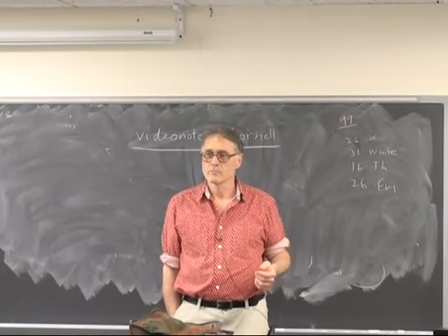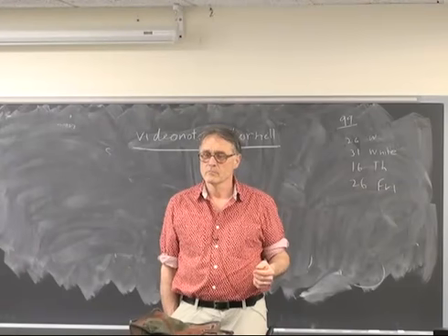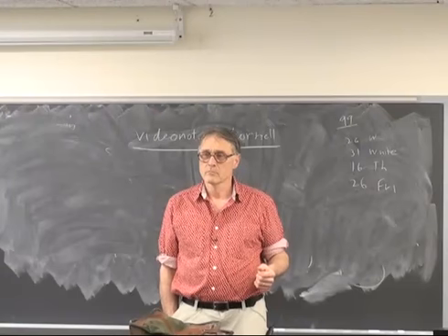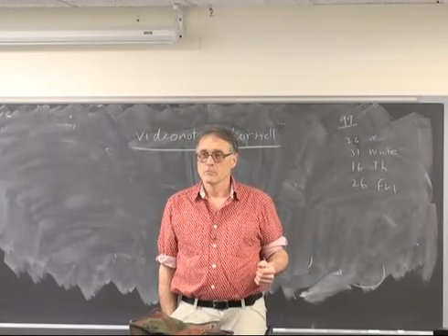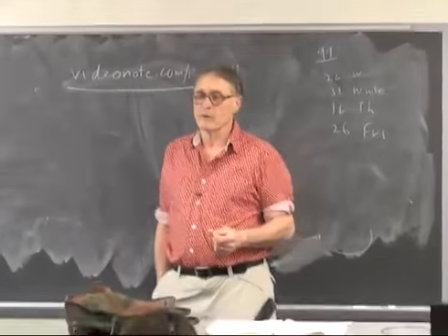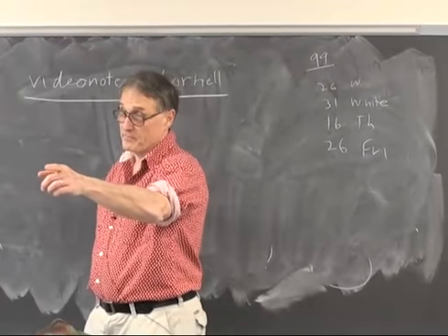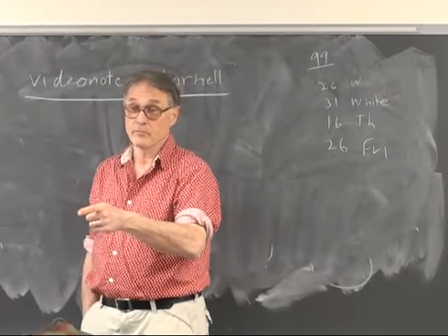I believe it's the question in homework 1, it asks you to explain the components which connect to a few specific pins. For example, this one pin called VCC is connected to a parent of like power regulator. Then we just simply say it's a power regulator. But also, VCC on the chip is connected to the power regulator and to 2 bypass capacitors to ground.